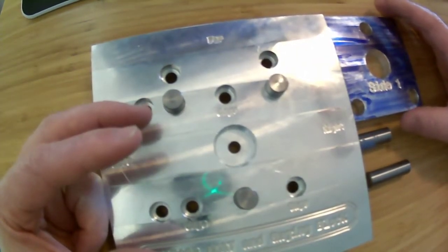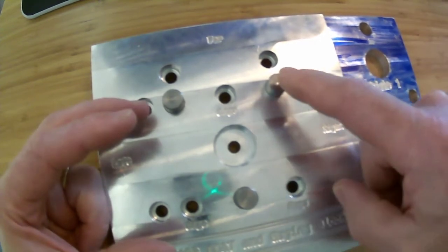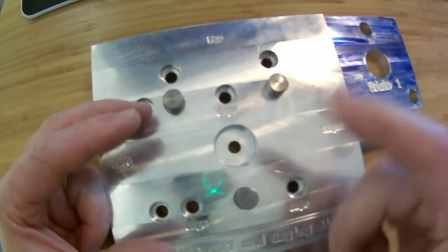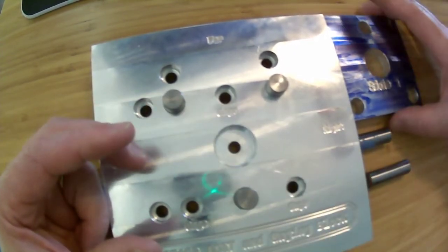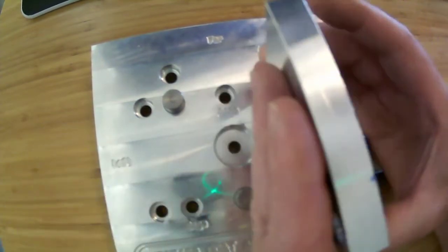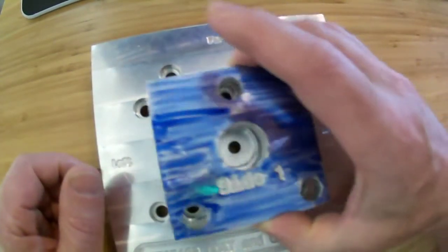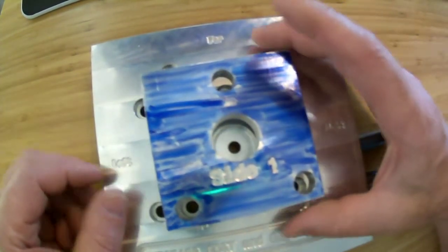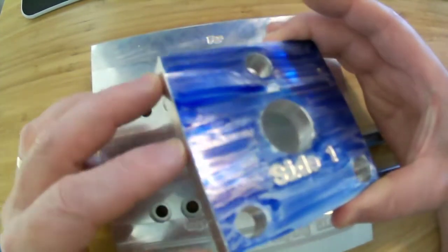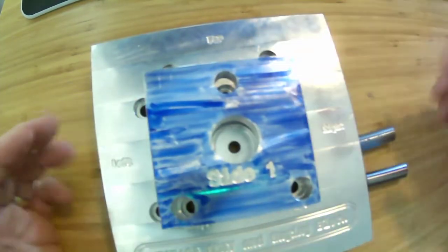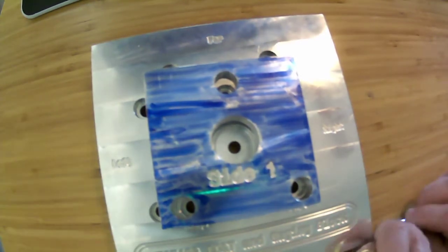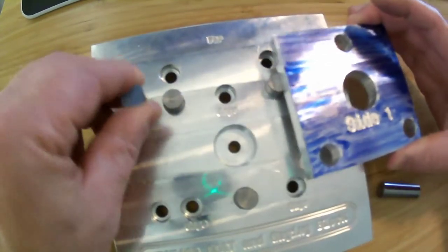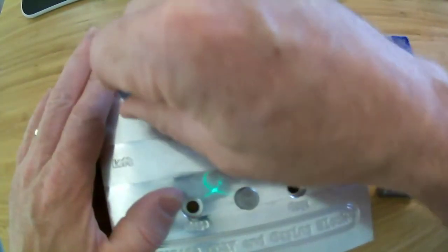The likelihood of me being able to get these 3 locations exactly perpendicular to these 3 is very small, and the likelihood of the back surface and the side of the part being exactly perpendicular is even smaller, and especially the surface finish in the places where I'm going to touch it, that is the smallest of all. So instead, we're going to touch it in 2 places on the second side. So I'm going to take these 2, hopefully.